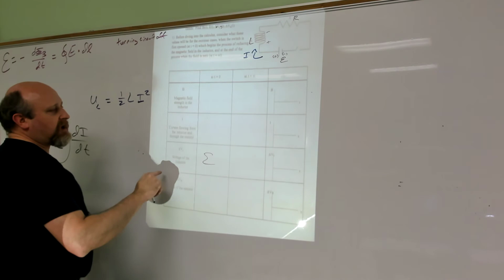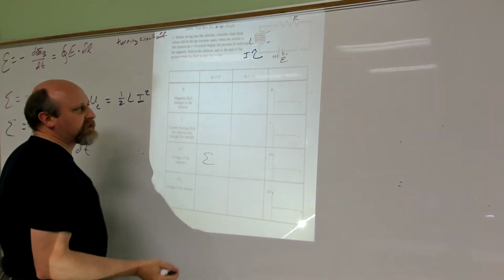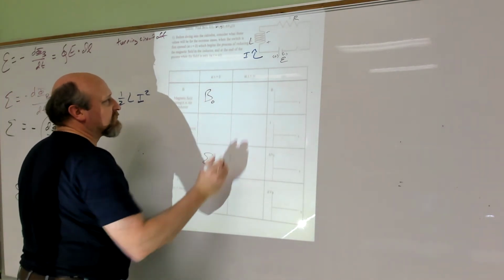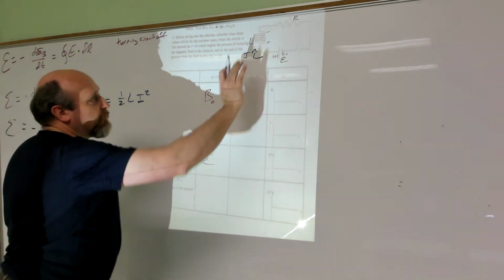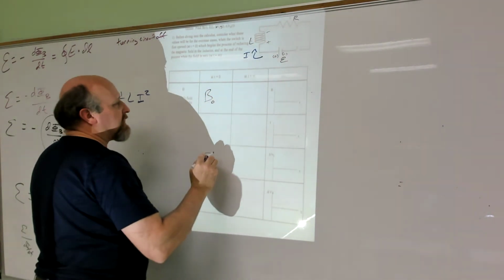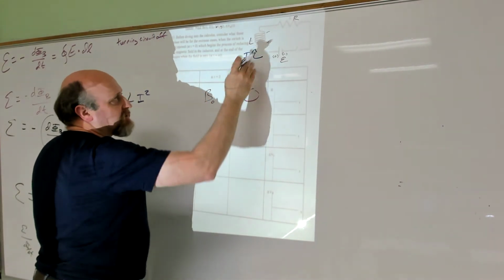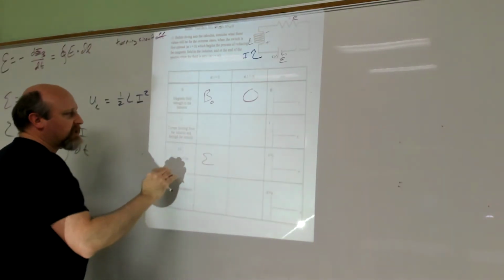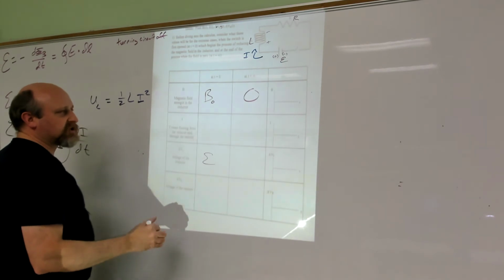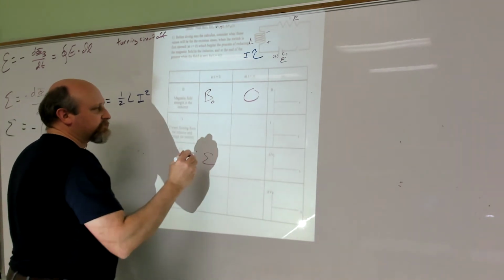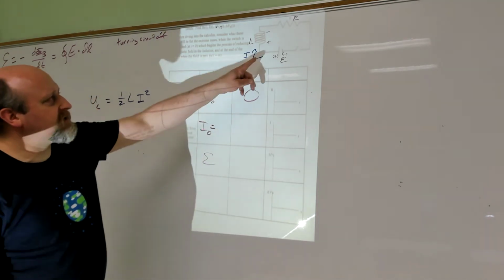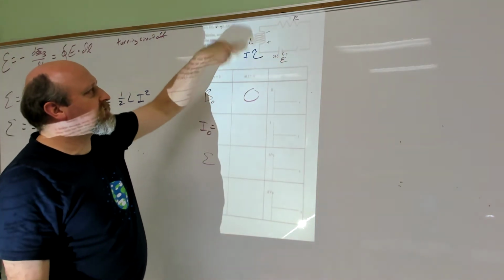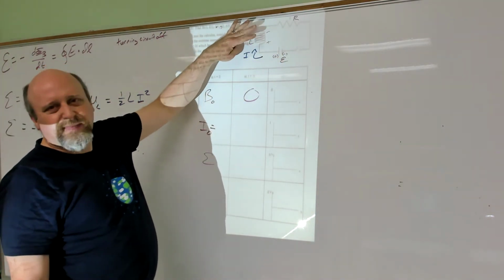There is going to be some magnetic field in that inductor. I'm just going to call it B0. The point is it's starting at what it was originally before someone opened that switch. At infinite time, it's going to go to 0. Eventually, the current will stop flowing. The current flowing at the start is just the initial current, whatever that was. In this circuit, if this had been running for a long time, we could say that was at its maximum value.